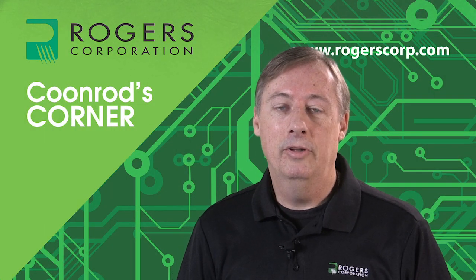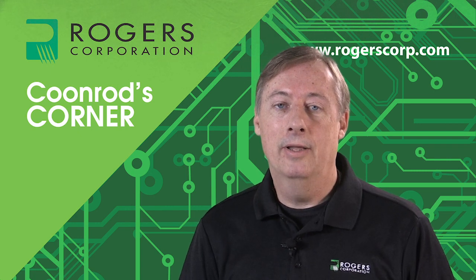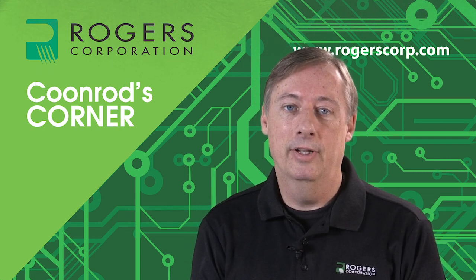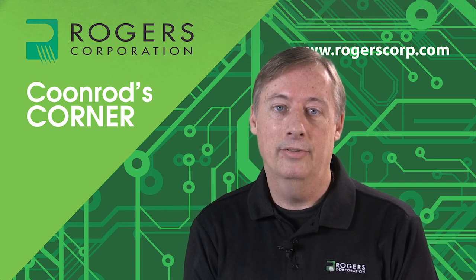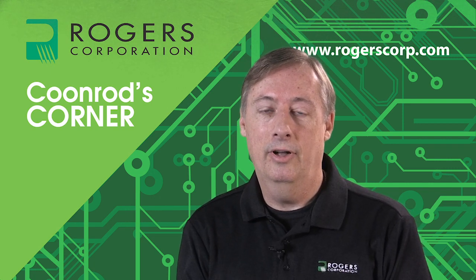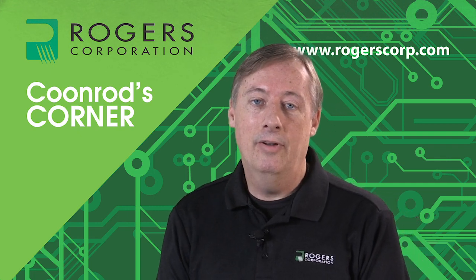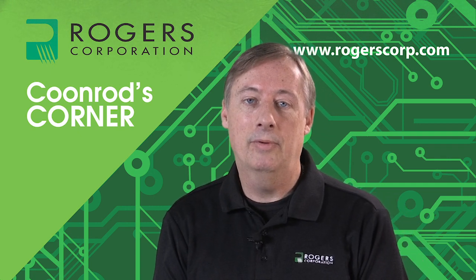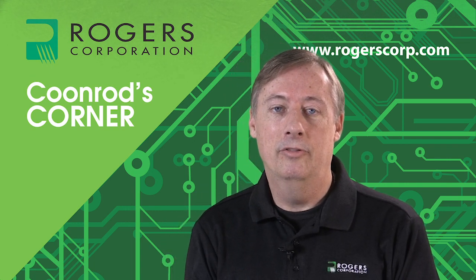In this video, I'm mostly focused on how to make the copper and also copper surface roughness. There's many other aspects of copper that are important to understand, such as how the copper actually affects the wire bonding process, and there are other things to consider as well. Now, besides the copper roughness affecting insertion loss, it also affects phase response and phase velocity, which I already mentioned, and it can have an effect on group delay and impedance.